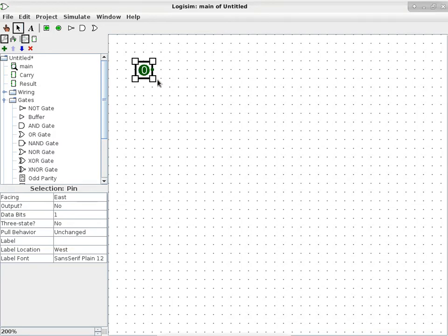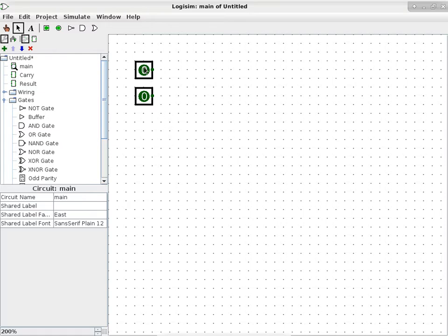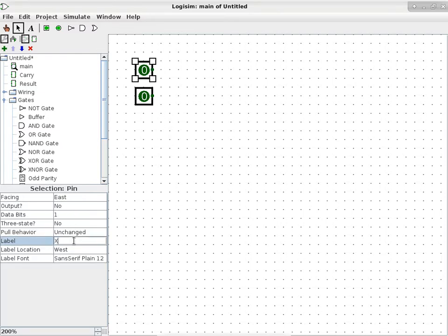And so we'll specify a whole bunch of pins here. Actually, I could do something like this. So we'll call this one X0, and this one is Y0. And then the output, so this is the first column. X0, Y0 are the bits that we are adding in the rightmost column in the class representation on the whiteboard. And then the eventual output of this is going to be labeled S0 because it's bit 0 of the sum. Is that okay?